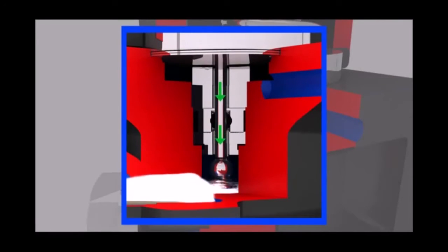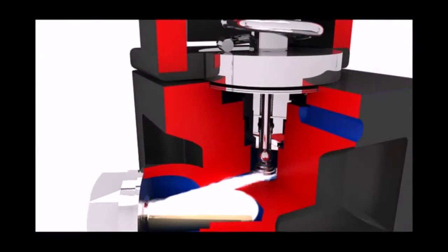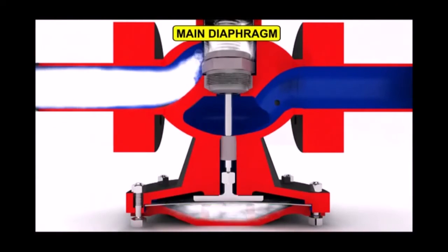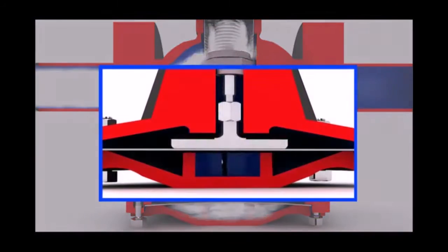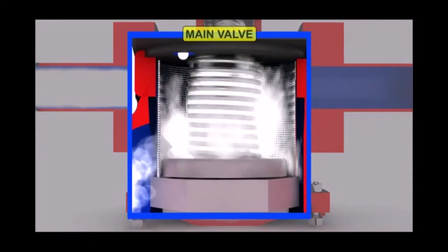This results in deformation of the pilot diaphragms, which in turn pushes the pilot valve plunger and SS ball against the spring located below, causing the pilot valve to open. Accumulated steam in the main valve chamber enters the pilot valve chamber through a strainer screen, called control steam. This results in reformation of the main diaphragms, which in turn pushes the push rod upwards and opens the main valve against its return spring and the supply pressure.